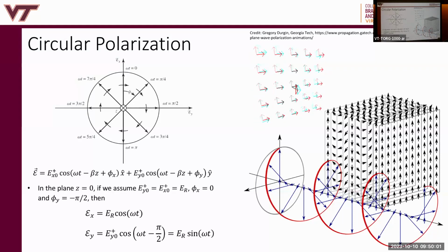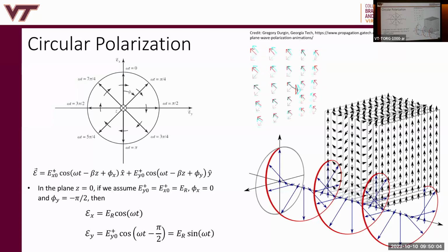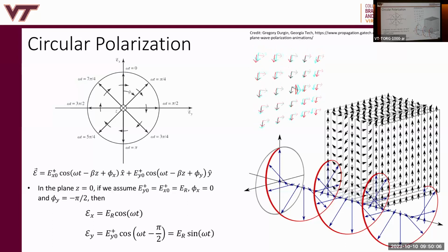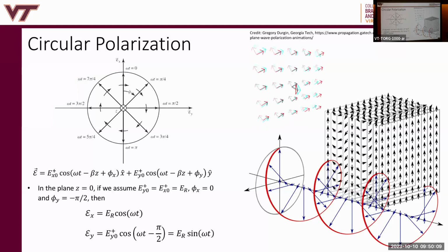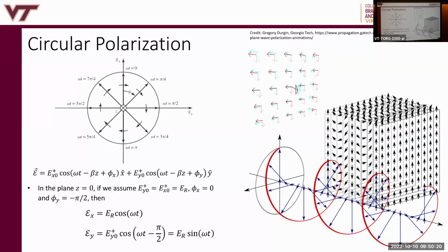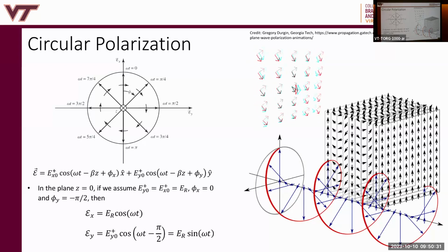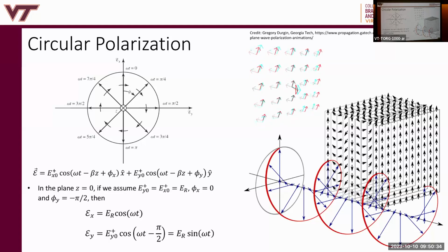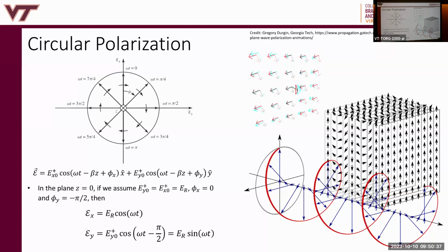Like, how do we decide if we have to make it right circular polarized or left circular polarized? That's your choice, right? So typically a system designer will come up with these properties, right? If you have a big project, they'll decide, okay, this polarization, maybe because it does better in the rain or some kind of property that they're trying to exploit based on which polarization they pick. But the system designer will do the study and the analysis of the channel and figure out which polarization is best. And then the antenna designer will make an antenna with that polarization. But LHCP and RHCP, very similar, right? They're just orthogonal. Okay, great.